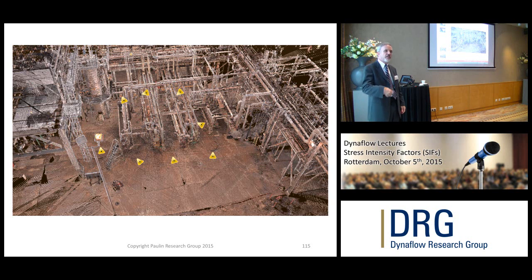And so what happens is there will be critical systems where when you scan them and then compare them to the Caesar results, they don't match. And so somebody guessed at a tower temperature for you that was just way off. Tower temperature wasn't anywhere near that hot. So the line only went up 1/4 of what the guy told you it would go up, which is typical. You want to know what the real thicknesses are.